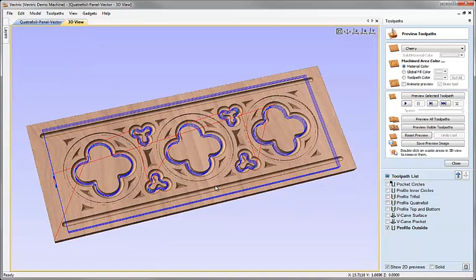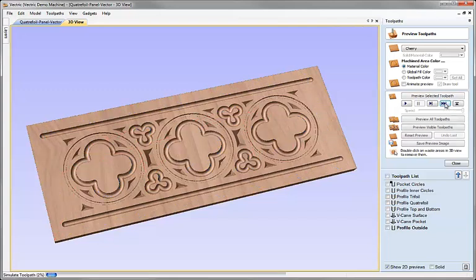Now we could go ahead and preview this toolpath. So we're in the preview, automatically went into the preview here. With that selected, what I may want to do is just check that it is going to cut all my interior vectors first. So the way I can do that is I can run to the next retract here. So if I click on that, I can see there that it's cutting each of the layers there. Then it's going to cut the next one.